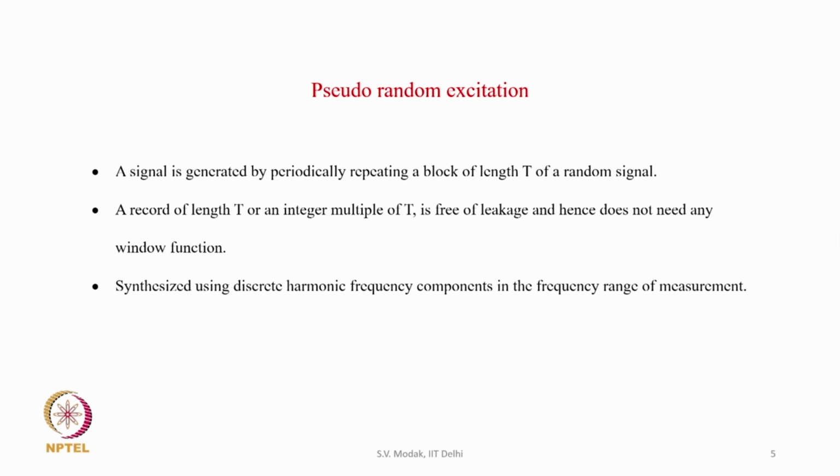It is synthesized using discrete harmonic frequency components in the frequency range of measurement. For the present case we have f max as 400 hertz, and a frequency resolution delta f of 0.25 hertz. So we have 1600 frequency lines in the spectrum.